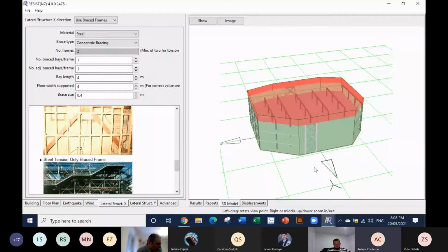From an earthquake engineering perspective, walls are the best and safest structural system. So I would always recommend students and architects use structural walls to resist earthquakes. But say, for example, your design concept was about transparency, then walls may not be a good solution. And cross bracing might be better. And so bracing can be designed and built to be safe. And so if bracing is better for articulating your concept, then that would be the better choice for you.